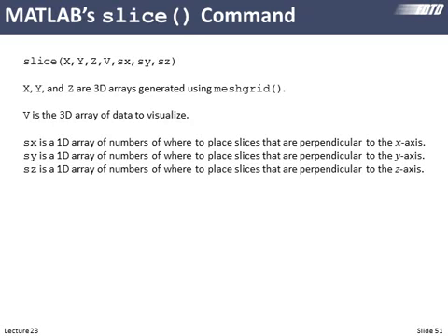So I tend, for most of my simulations, just like to slice through the middle of each axis. So I'll just set these to usually zeros. If my axis goes from a negative number to a positive number, I would just set these to zeros. If your axes are going from 0 up to some positive number, then you'd want to set these at the midpoint, just a single number for each. I think that looks best. There certainly are circumstances that you want to probe the field in other planes, and you'd stick in other values at that point. But a good place to start is just a single value in each one to be the midpoints.